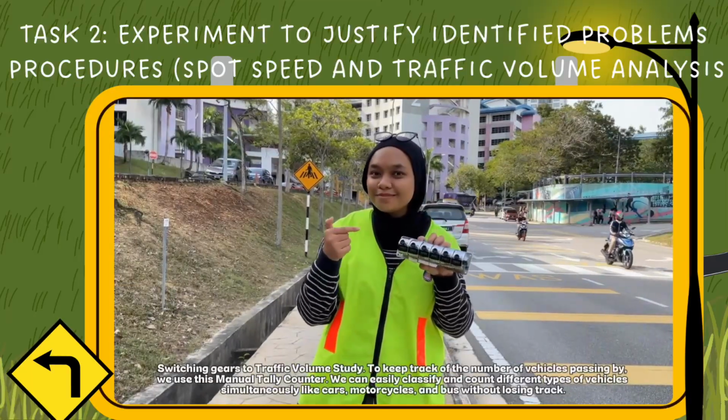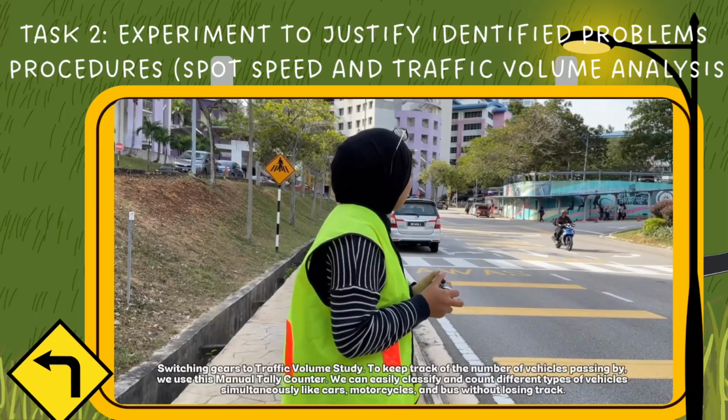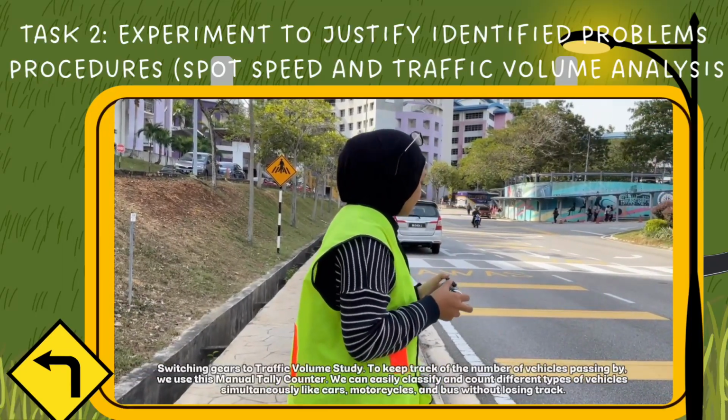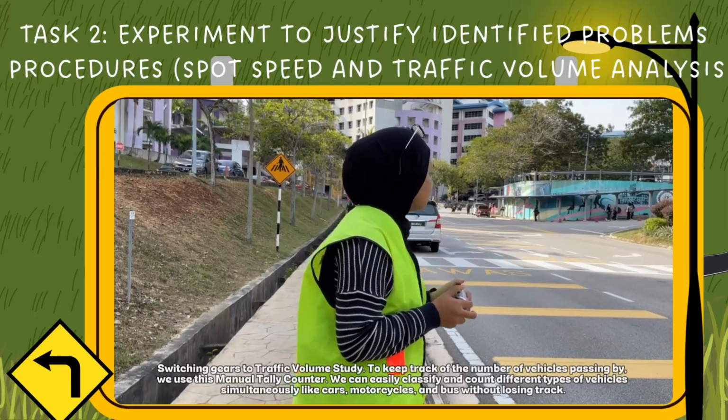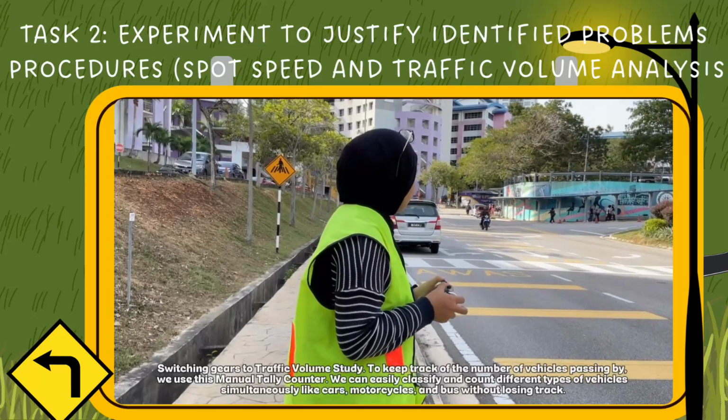Now, shifting gear to our traffic volume study. To keep track of the number of vehicles passing by systematically, we use this multi-unit manual tally counter. Each clicker button is designed for a specific vehicle classification, like motorcycle, car or bus, so we can count them simultaneously without messing up our data.